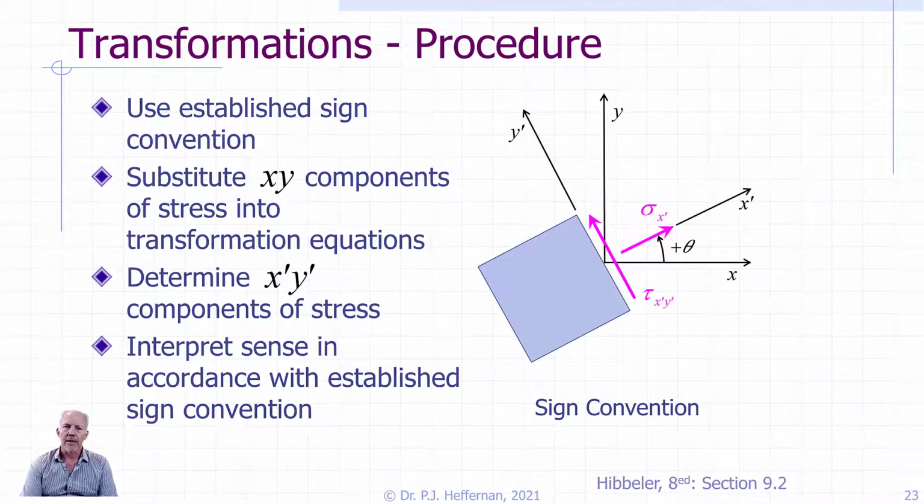We also see the sign convention for the stresses. So for normal stress, positive is tension, compression is shown as negative, and our shear stress is positive face, positive direction, negative face, negative direction. Those are both positive. If they're opposite, so positive face, negative direction, or negative face, positive direction, they would be negative. And that would determine the sign of your in-plane shear stress.